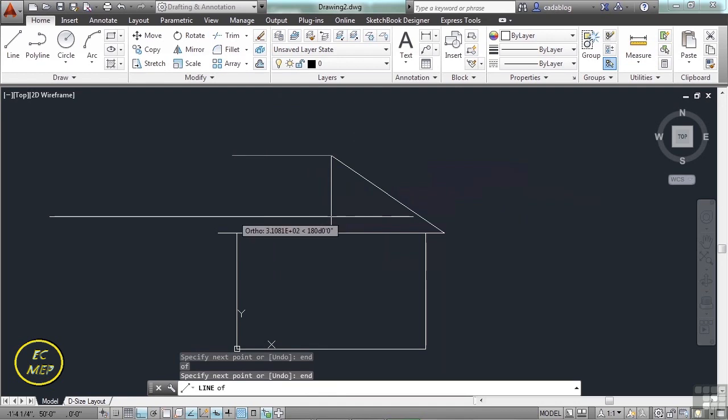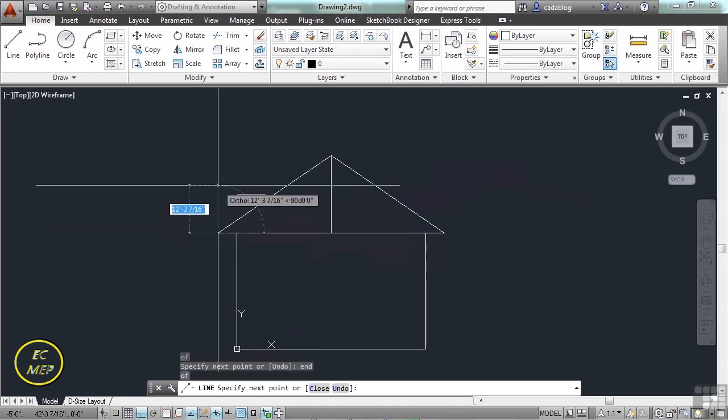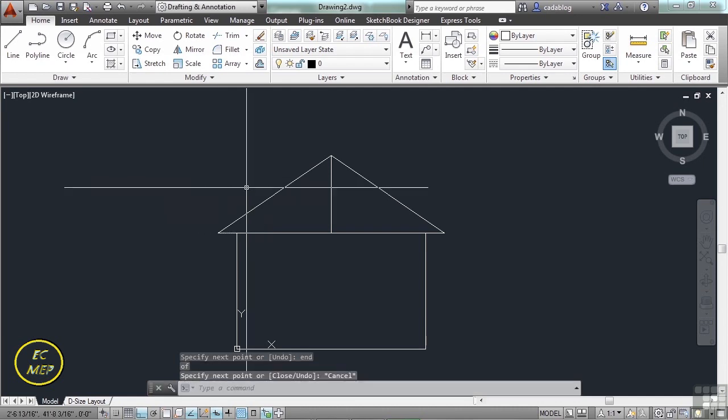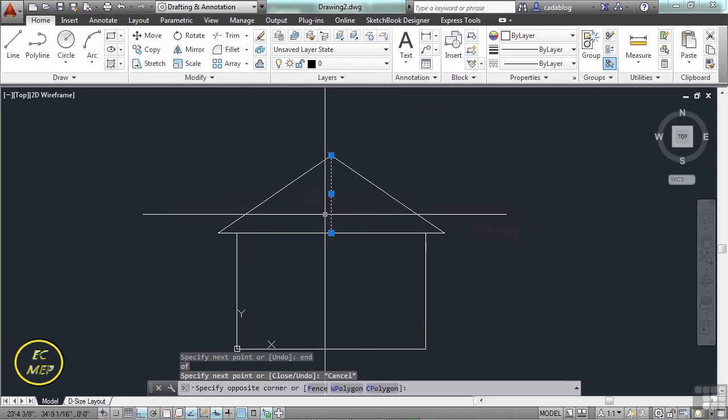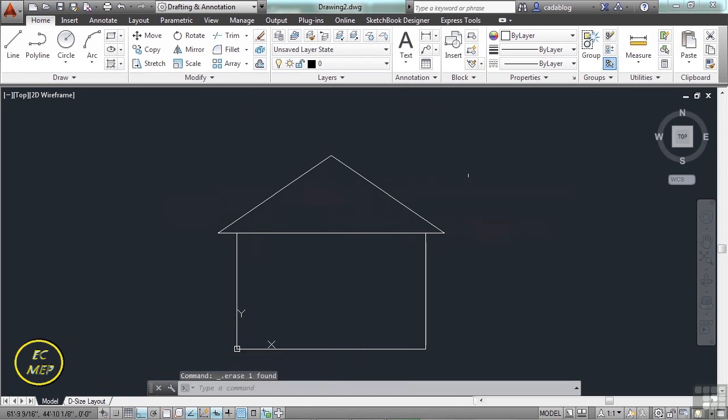And if you mess up typing in the dynamic input, you can always go back. If you type in something that's not possible that AutoCAD doesn't know what to do with, you saw that red box come up and it says, hey, I don't know what to do with this, please tell me again. And that's fine. You can backspace or delete what's inside there and type again. You can also use your arrow keys to navigate inside the text, as you can see there through my examples. And there we go. Now we can delete that line. And that's basically it in a nutshell.